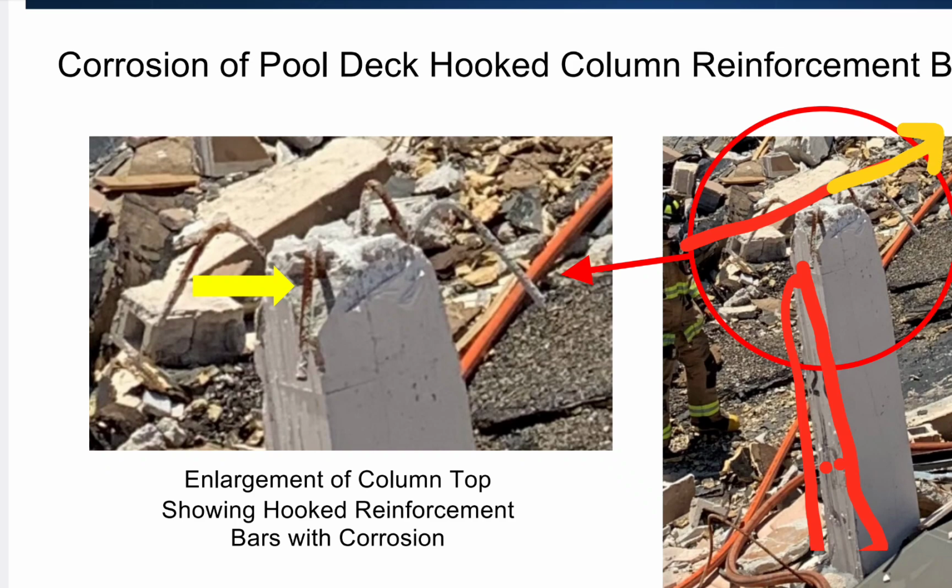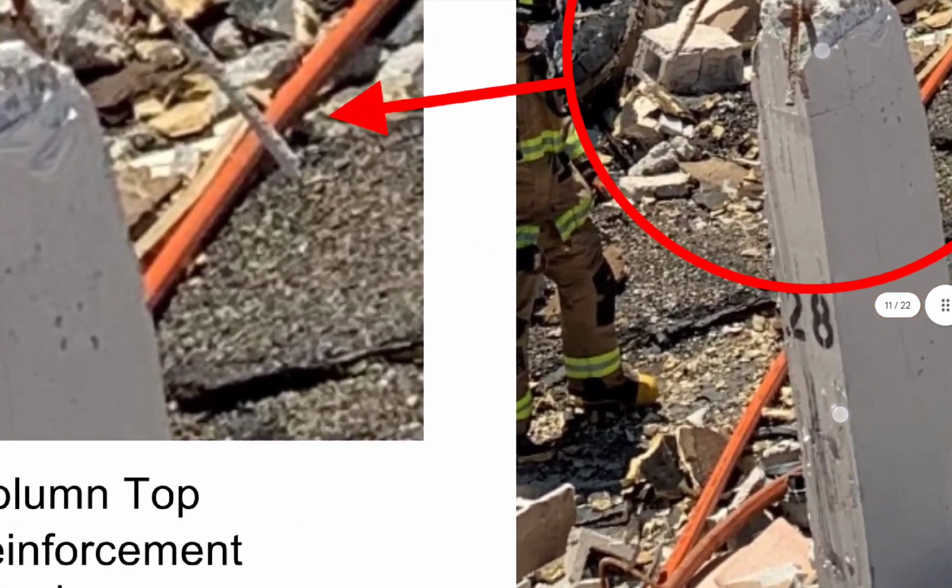And this anchorage over here is what became loose. And we know that because if it became loose there, when this goes down, it rotates over. The deck rotates to this side, pulling that long piece of steel with it. Drag, I'm going to remove the stuff, scratching down here and coming to rest. Scratching off the face.